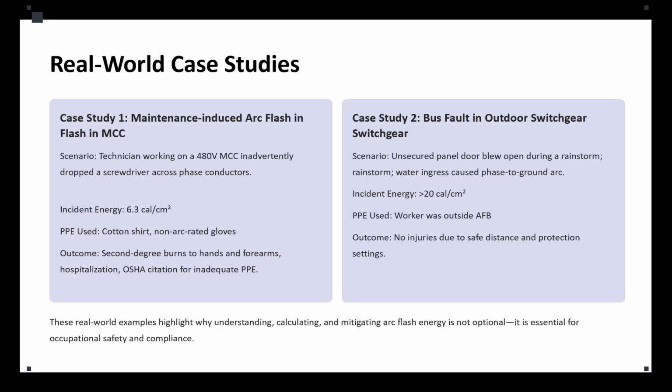Because of that, an arc initiation happened, and it happened vertically inside the enclosure. Okay, so the configuration, as we said, is vertical conductor in a box, VCB configuration in IEEE 1584. The arc propagates through the interior and vaporizes a portion of the bus bar, triggering the protective device operation.